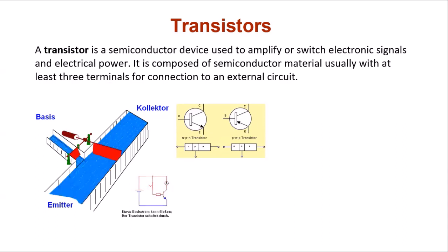The NPN and PNP is actually the name convention of the transistor because of the materials used. In the previous lecture, we had seen the concept of diode, wherein we know that we can use P-type and N-type semiconductor materials to form a diode, also called a PN junction diode. So there are two types of semiconductors used to create the component diode, P-type and N-type.